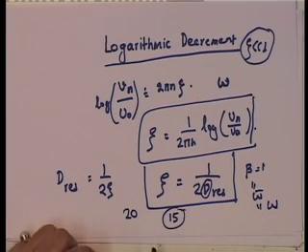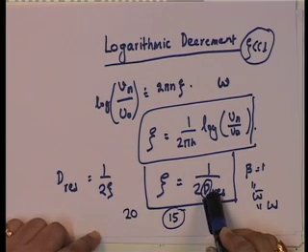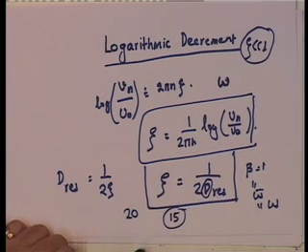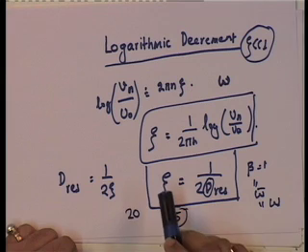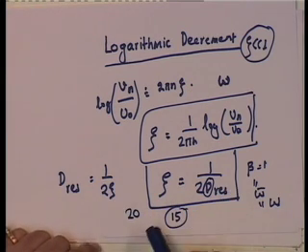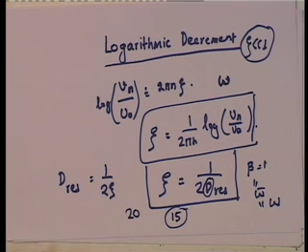Think of the error in the xi value. If you use 20, it becomes what? 1 upon 40, so that is 2.5, that is 2.5% damping. Whereas if it is 15, what does it become? It becomes 3.3% damping.